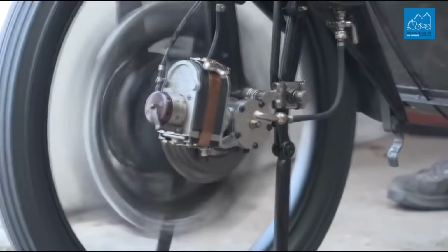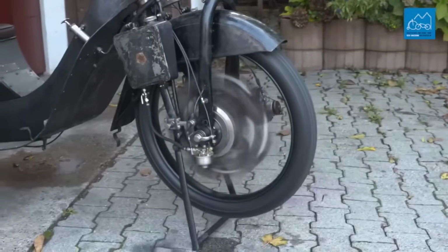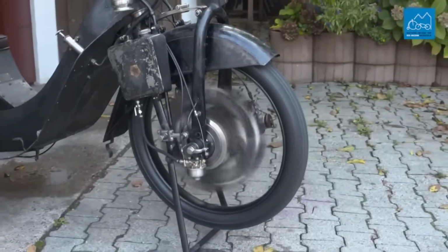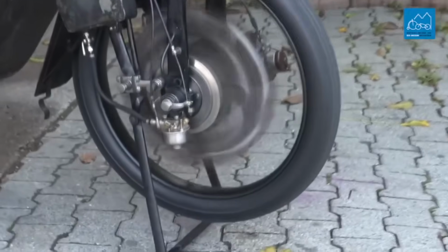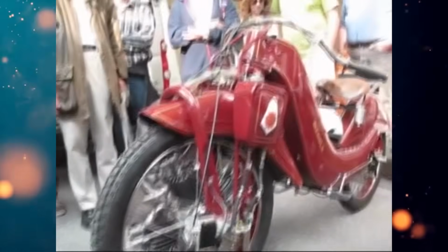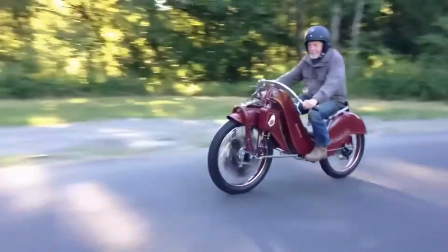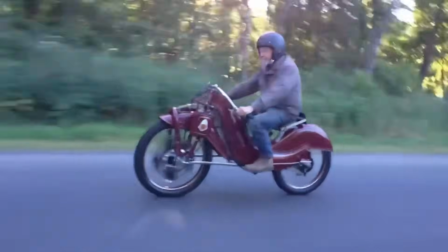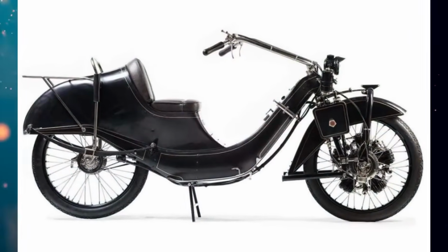The crankcase was firmly attached to the wheel, and the crankshaft rotated 6 times for each wheel revolution in the opposite direction. This design made it possible to significantly reduce the gyroscopic moment of the motor wheel, which weighed about 30 kilograms. The Megola's chassis was also unconventional, made of load-bearing curved riveted steel sheets. The rider sat on a comfortable saddle with a backrest, or in the sport versions, on a regular motorcycle seat of that time. The Megola touring model featured rear leaf spring suspension.